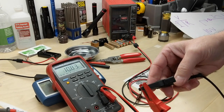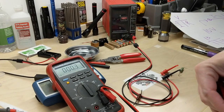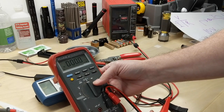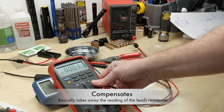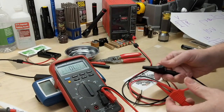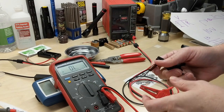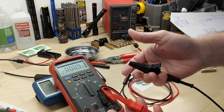We put the leads together, it's showing about 0.2 or 0.3. If we want to get real precise, we can hit the relative. The triangle will show up on the screen also, and that gives us a little bit better measurement.